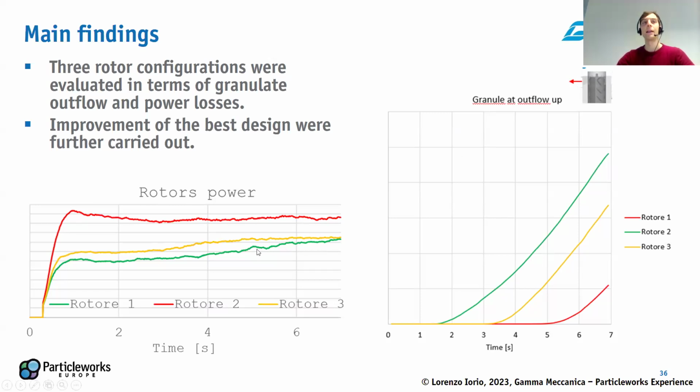You can clearly see, and this is an output of the software, it lets you predict torque on elements or resistive forces on every element you have in the simulation, and compute power, resistive power. So you can see the separation efficiency and the total consumption of power. So the green design was actually better suited.